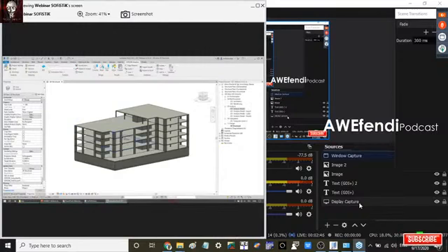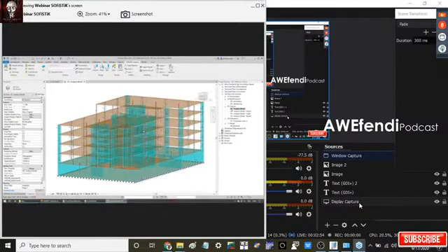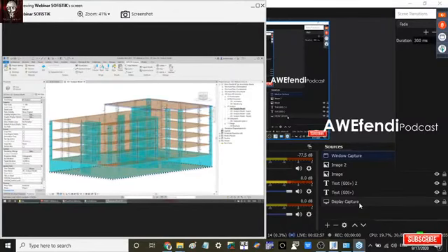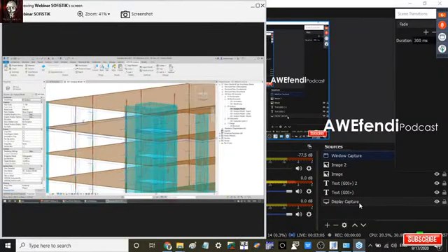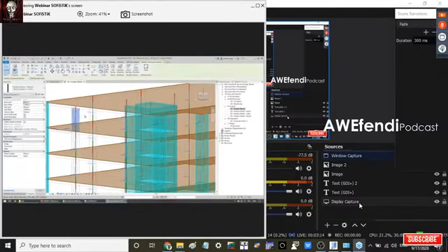As already said, I assume that I got this model from an architect, and I think most of you are familiar with the fact that Revit, when switching now to a different view, already provides a structural or an analytical model in parallel to the structural one. So you can see that in this view, which displays the physical elements in a transparent view, and in parallel to the physical elements, you already can see the analytical line of this physical element. This is essentially a kind of a property, so I could also switch it off in order to ignore this element, for example, in analysis.